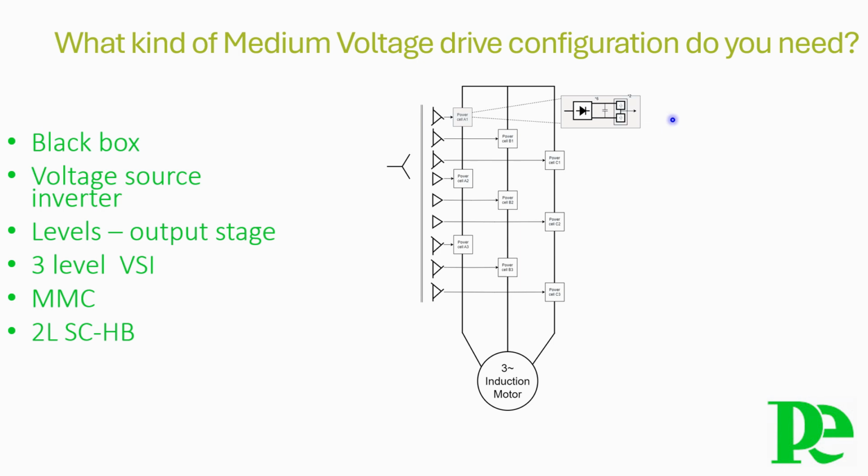Many applications, including low voltage drives, use low voltage IGBTs. They are manufactured in very high quantities. Medium voltage drives that utilize low voltage devices can take advantage of rapid innovation cycles, exceptionally reliable components, and a sustained availability of spare parts. The result of adding up the output of multiple low voltage power cells is a high quality output voltage providing